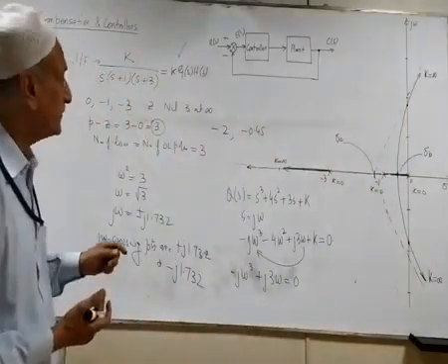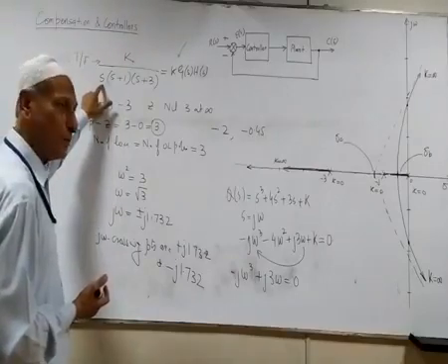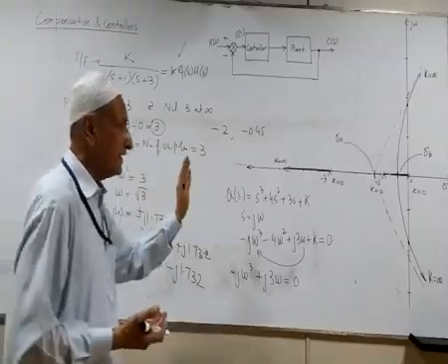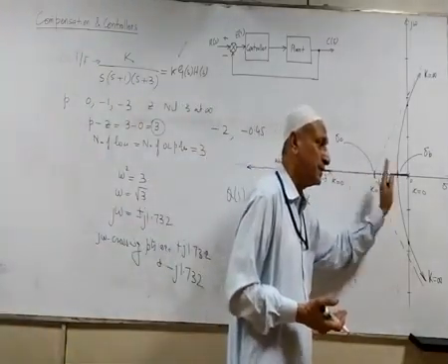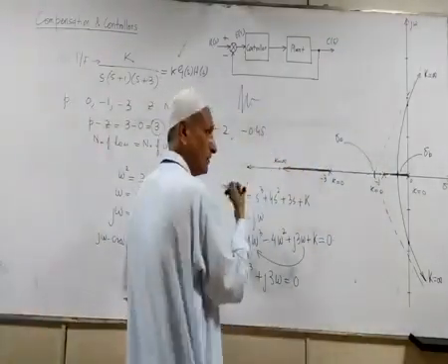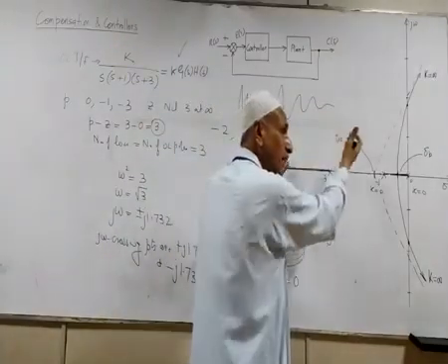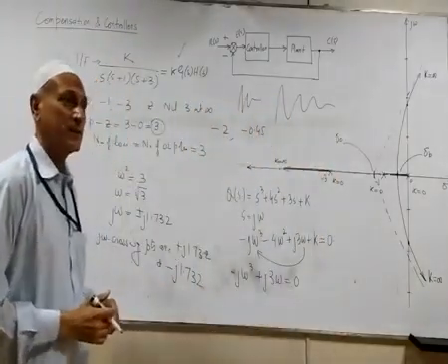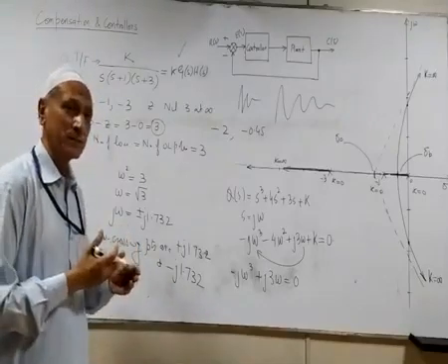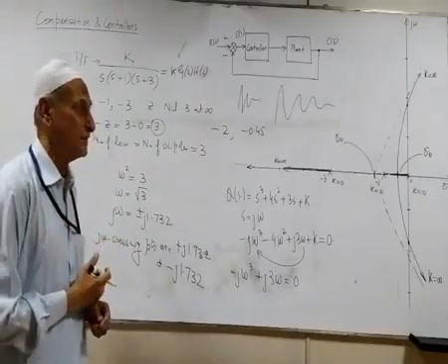So what we have done actually is simply adding a pole at the origin. Now it has a twofold effect. The first one is that the entire root locus is shifted towards the right. That is, the transient response, which was something like this in the previous case, would now be something like this, that is, a longer duration transient. This means the disturbance will not die out quickly. It is a slow acting system in terms of rejecting the disturbances.